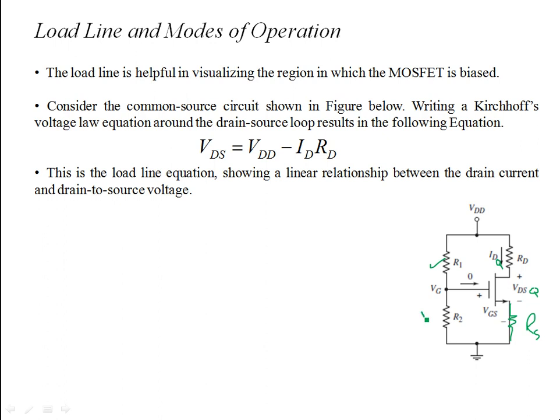For the purpose of DC analysis, we don't have these physical resistors in the IC. What we have is these resistances R1, R2, RD, or RS. They're again MOSFETs. We do have non-linear IV characteristics for MOSFETs, which we can model as a resistor.